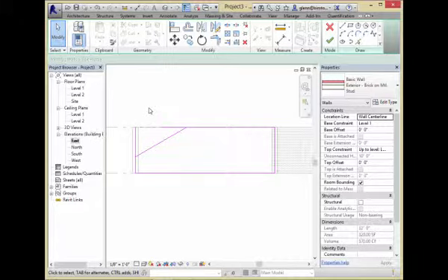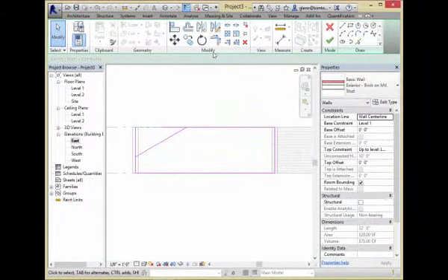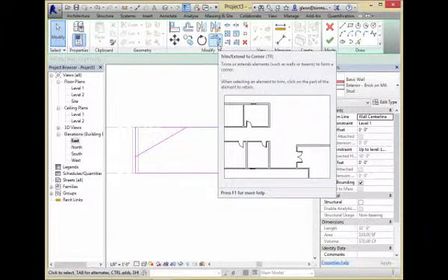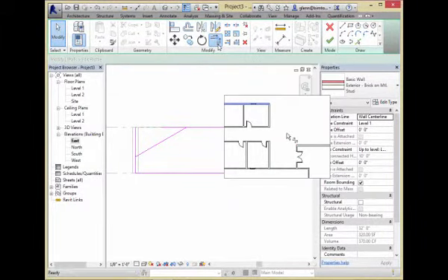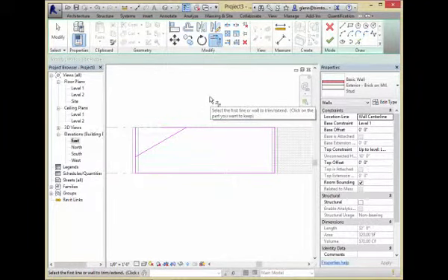So if you have a line selected, you'll see there's a trim tool. Actually, I think it's even there if it's not selected. But trim has a shortcut, TR, so if you ever hear me saying TR trim, that's what I'm referring to. Just get the tool. And here's the way the trim tool works. It's actually kind of intuitive, but if you've been doing a lot of drafting with AutoCAD, it's backwards the way you think it should work.